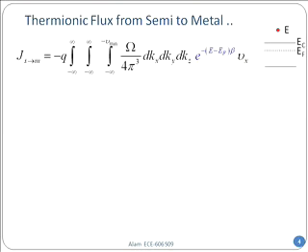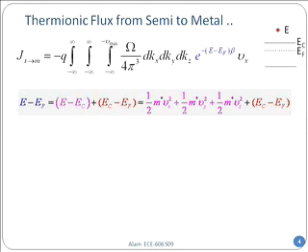So now let's look at the Fermi factor, E minus EF. E is some energy above EC, and you can see EF, and that's the occupation, right? The Fermi function or the Boltzmann function at a given value of energy only depends on E minus EF. So you can split it into two pieces. One is E minus EC, from the edge of the conduction band to the energy of the electron, and the other is EC minus EF. Just these two pieces. Now E minus EC, what is that? That's the kinetic energy. Do you remember that we did this kinetic energy and potential energy business before? So E minus EC is the kinetic energy.